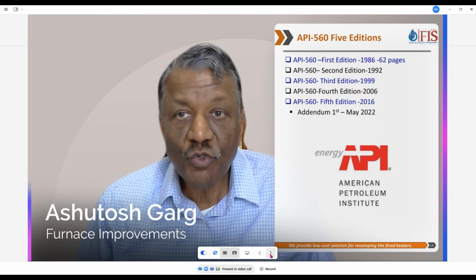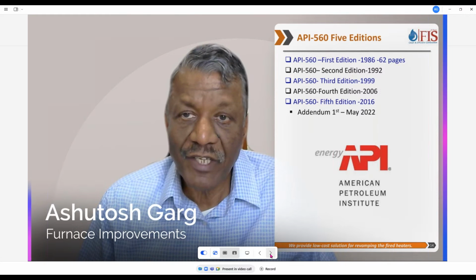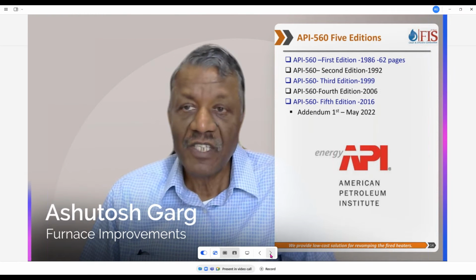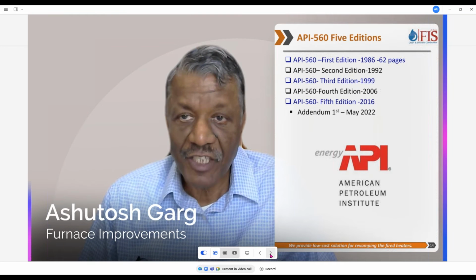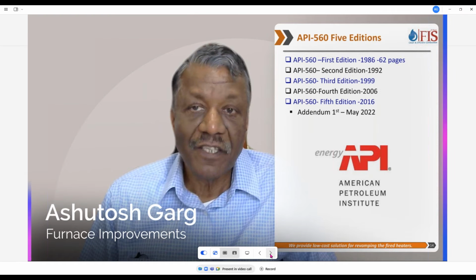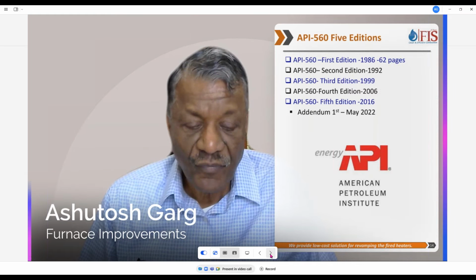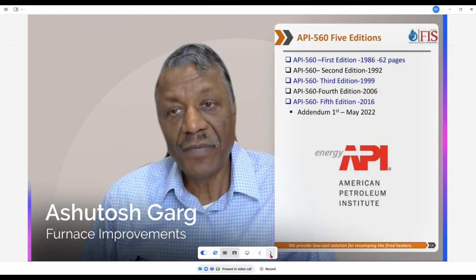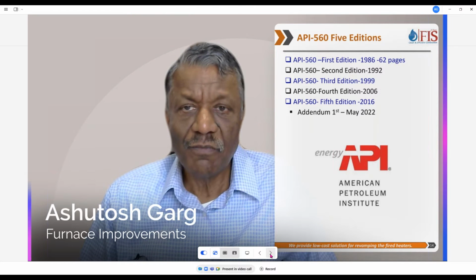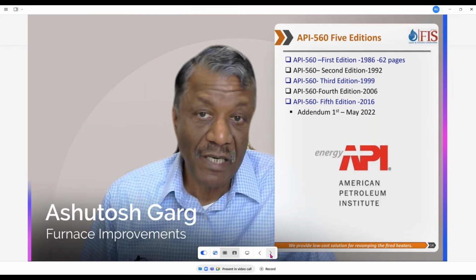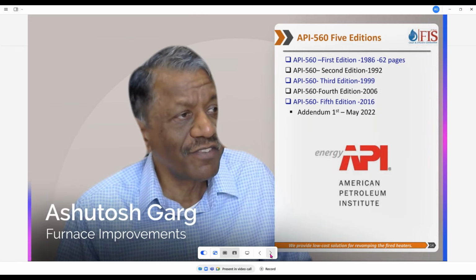The first issue came out in 1986. The second edition came out in 1992, and since then we have got 3 more editions issued in 1996, 1999, 2006, and 2016. It is undergoing revision, and I believe a new document will be issued in the next couple of years. API has also started the practice of issuing addendums now. And for most non-critical heaters, you can buy a good heater with just the process data sheet and ask the vendor to follow API 560.